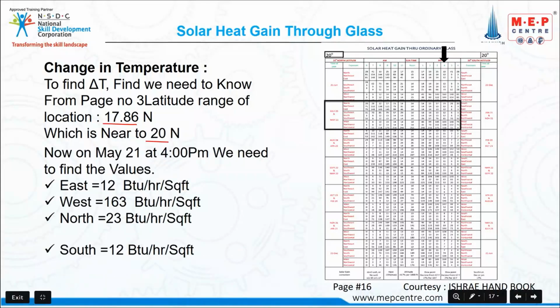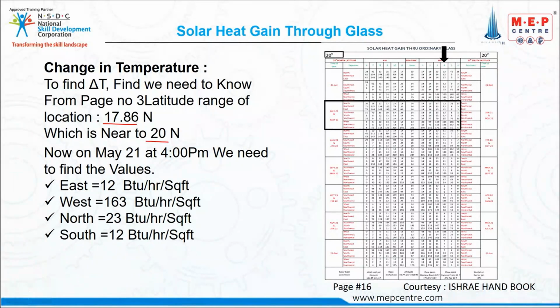So you need to remember this point. Sometimes nowadays in construction, the structure is constructed but the wall is not constructed. They fix the glass. Glazing will be done. So when you are taking the glass, the whole area you need to consider in the load calculations here itself. Not window. How much area is exposed, the glass area, you need to take in the calculation itself. Hope I am clear, right? Everyone, I am clear?